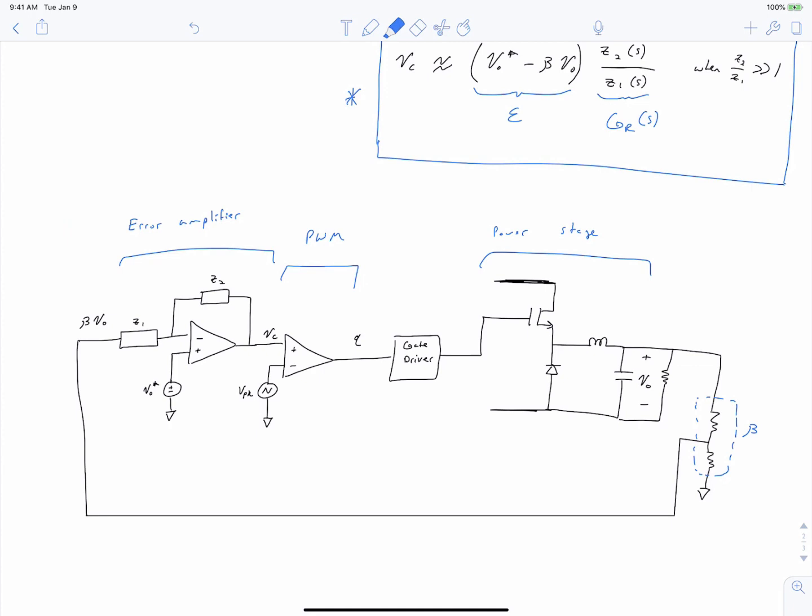You are now in a position where you're able to actually implement feedback control or regulation of a power converter using an op-amp. You know everything you need to know, from how to derive the small signal model of your power converter, to how to sketch the Bode plot of the loop transfer function and design a suitable regulator, and then how to extract the transfer function of that regulator from your Bode plot and then realize it with an analog circuit.